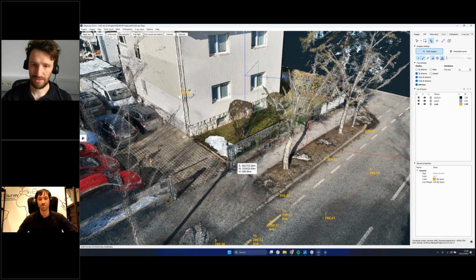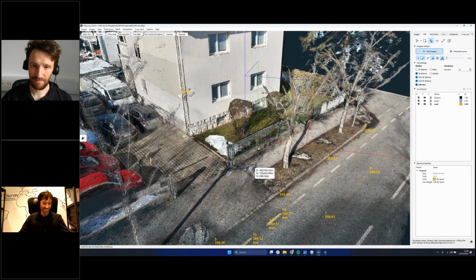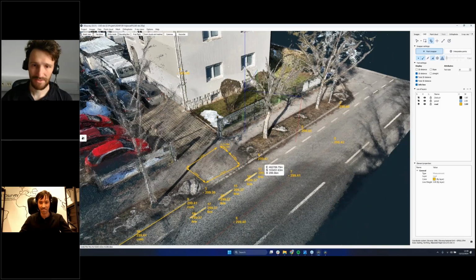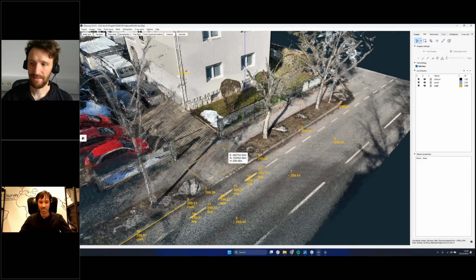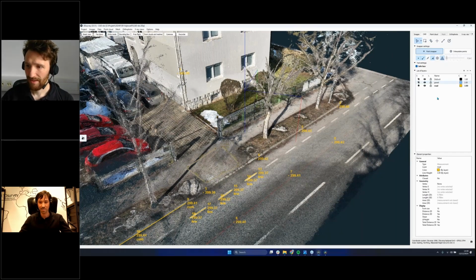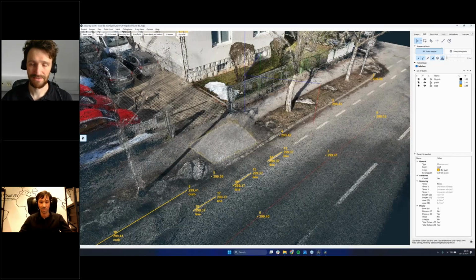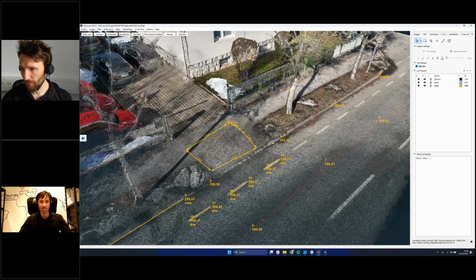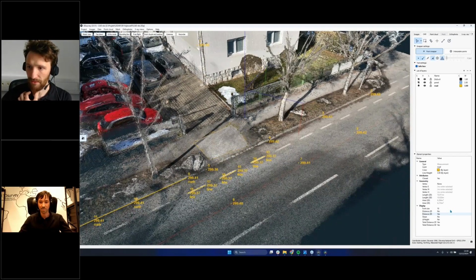And perhaps the final thing, maybe sometimes you're working with some areas and you misplace your last vertex. What you can do is select your polyline, and there's an attribute closed. You can just set it to yes, and it will automatically connect it, and you see you got this area selected now. Before, the area was not calculated, but now it is. It's right here.